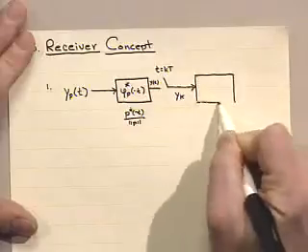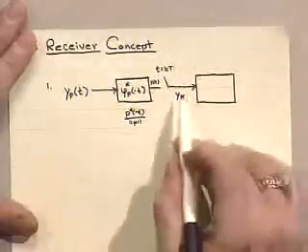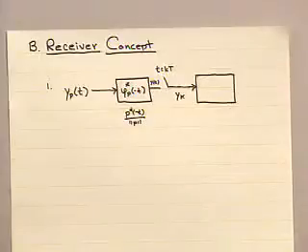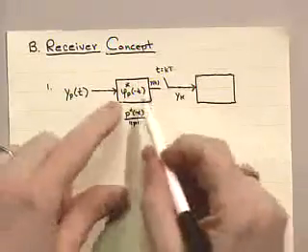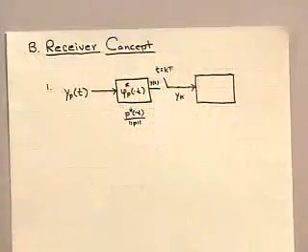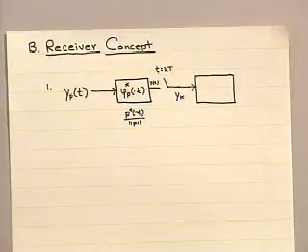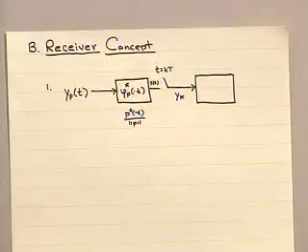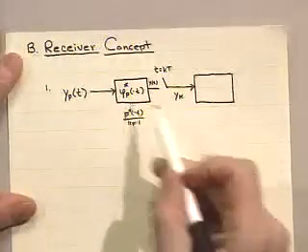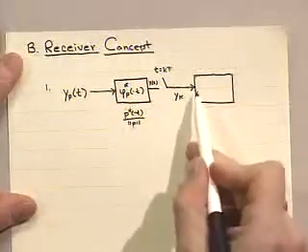I break ranks with everything I've seen earlier. At this point we really haven't lost anything in terms of optimality. We know that we can go through a set of match filters. If I think of this p star of minus t here in this sampling device as simply a set of match filters in time, I could always do a linear transformation on that to some orthogonal basis function. I could do Gram-Schmidt on the whole set over time, get a set of basis functions, and I would simply have a linear combination of one set of basis functions being these functions here. So I haven't really lost anything going through the channel at this point.